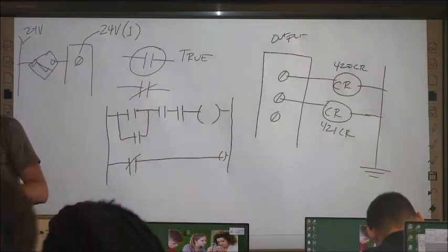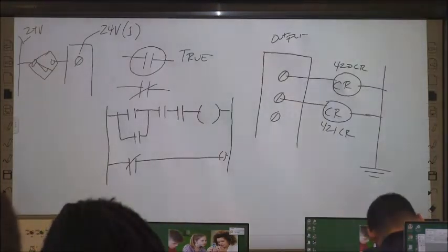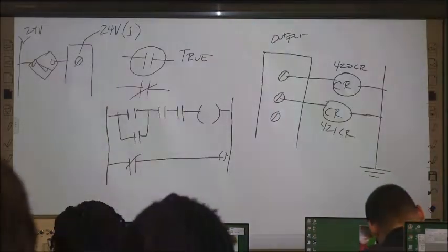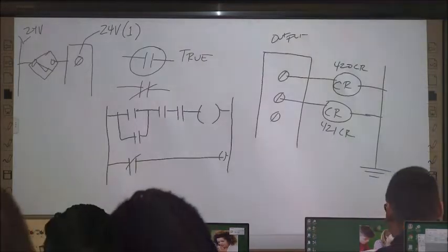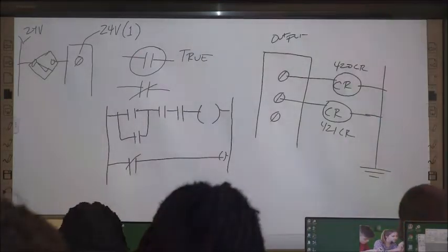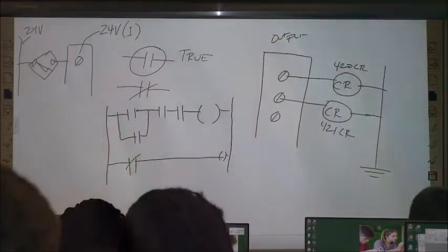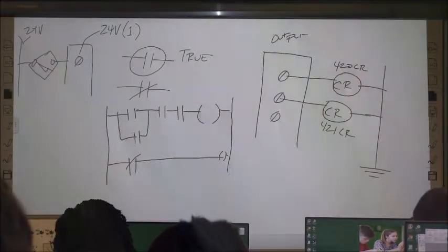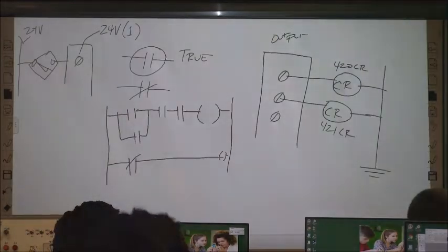Now, how did you come up with that? Explain that. Because pretty much everything's going to be contacts and coils unless it's a control relay thing. Because you need logic continuity on PB2, right? Yeah, I think a lot of you got this. LS, the limit switch, you've got to have logic continuity on that for the power though. Push button 1. Yeah.